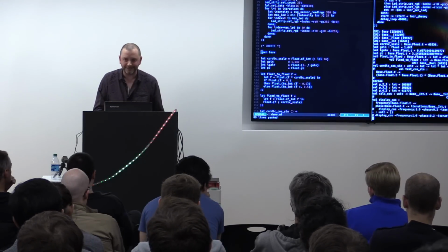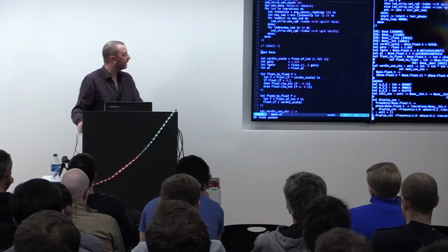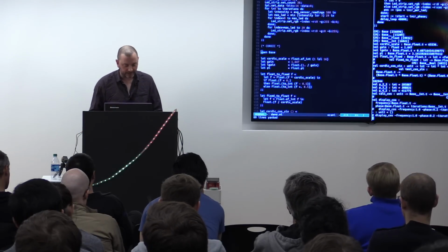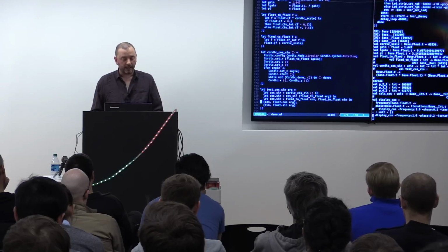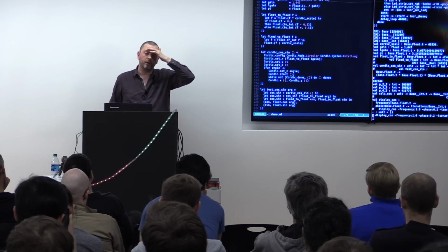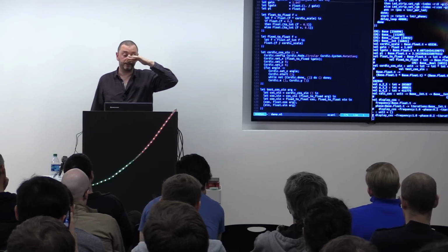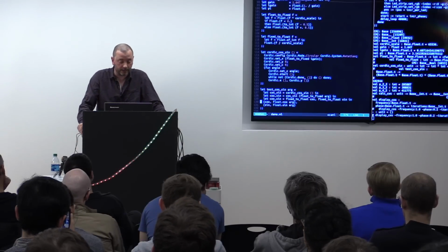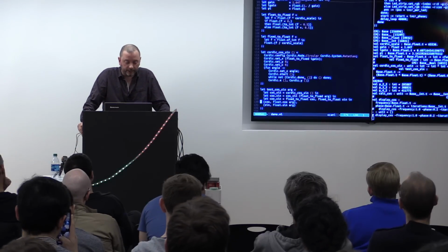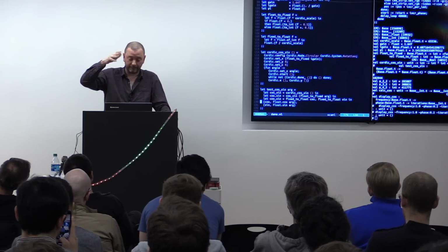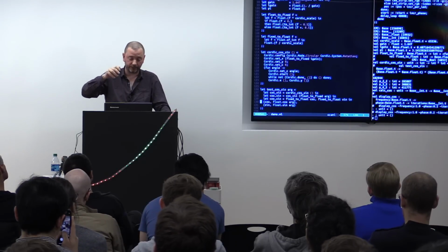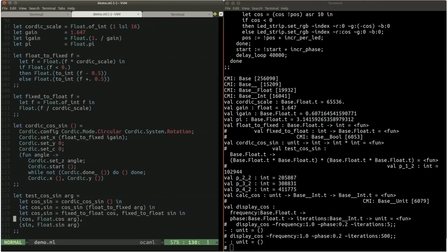Running? Yeah, great. So this one's a bit more complicated and not as much fun, I'd say. But anyway, here we're using the Cordic core that I mentioned that's in HardCaml as well. The Cordic core is actually pretty general. It'll do all sorts of functions from ATAN2 to hyperbolic functions to coordinate rotations. Here I'm using it the simplest way, which is just to calculate cosine.